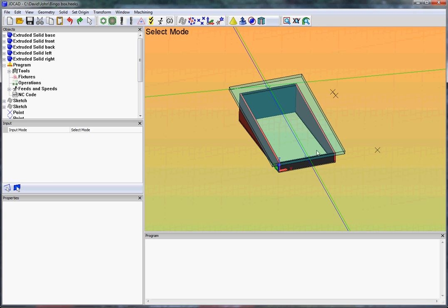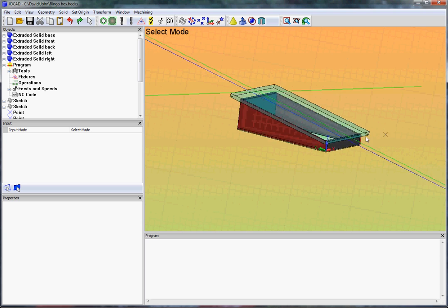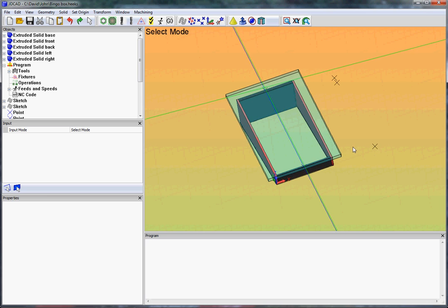this plane, if you can see that, like if I'm working on this plane here, that's a flat face, but this top is an inclined surface. But if I want to machine that, if I want to put a board flat on the milling machine and machine that out, then I need to consider that this is a flat plane, and that this flat plane here will marry to the flat plane of the XY plane of the milling machine when we start. So the way you can do that, let's just generate some G-code.